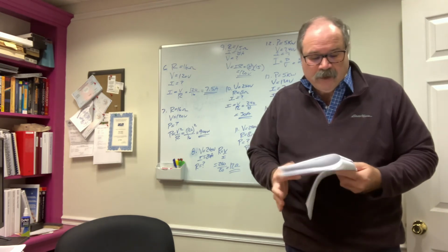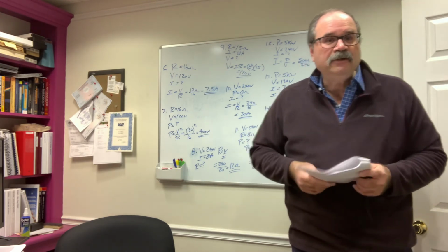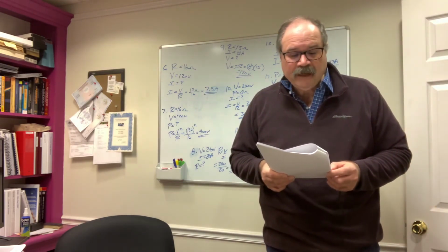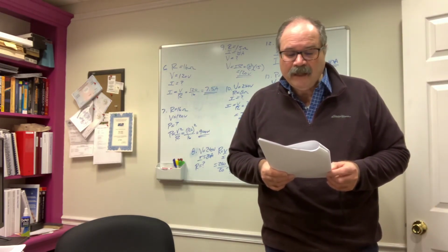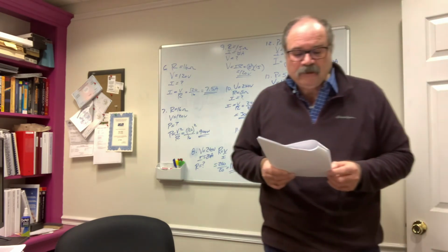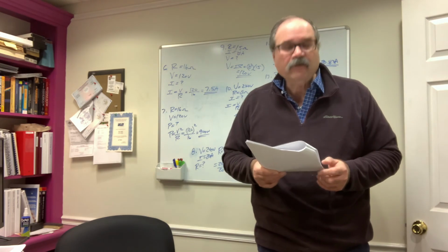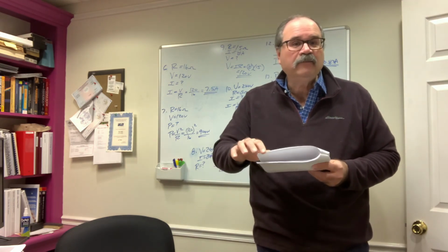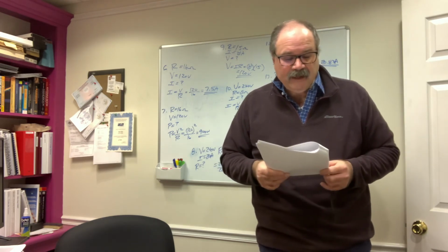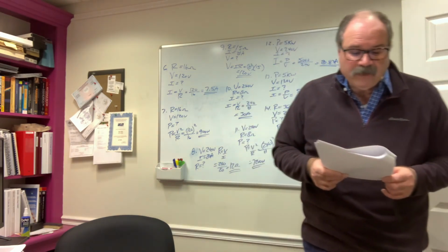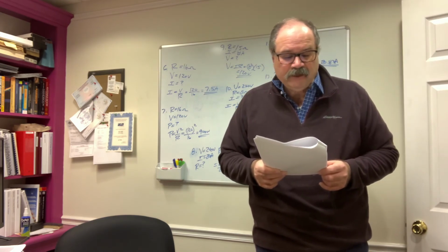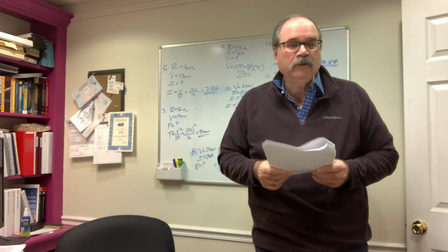All right, the remaining questions I will just give you the correct answer to using the same techniques you've seen with Ohm's law. Question 15. A 1500 watt heating element has a resistance of 38.4 ohms. How much current is flowing through the heating element? So the correct answer for current would be 6.25 amps. Question 16. A 1500 watt heating element has a resistance of 38.4 ohms. How much voltage is applied to the heating element? 240 volts.